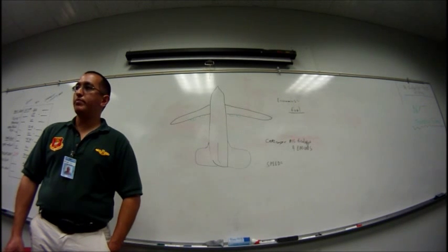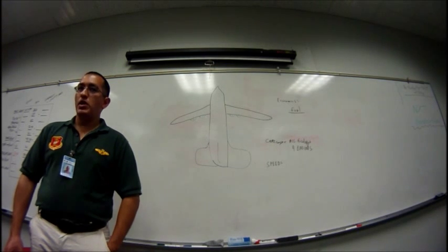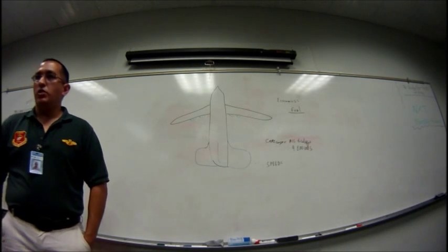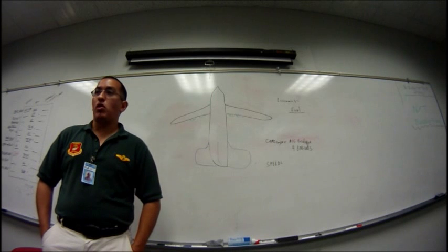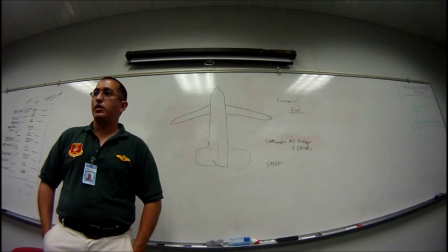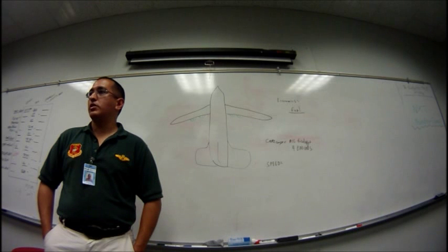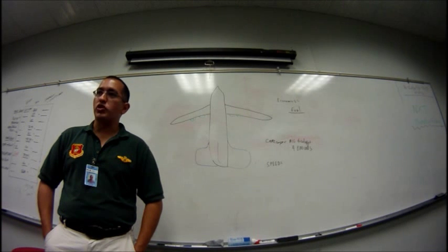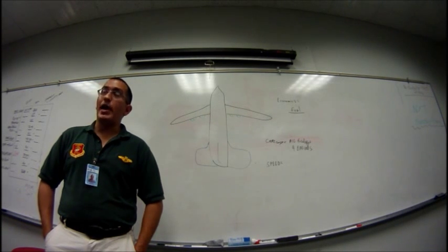Okay, well, what's better than aluminum? Titanium. Okay, they use titanium, right? But why isn't everything built out of titanium? It's rare and it's really expensive. Well, it is expensive. A lot of the expense comes from the manufacturing cost, because to weld titanium, you've got to be in a room that's purged of gas and filled with argon. A lot of people just don't have the infrastructure in place for that. Well, argon's an inert gas, basically, so they don't have the infrastructure.